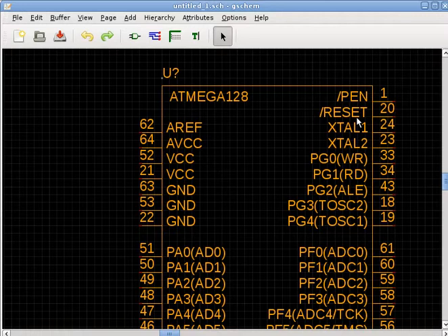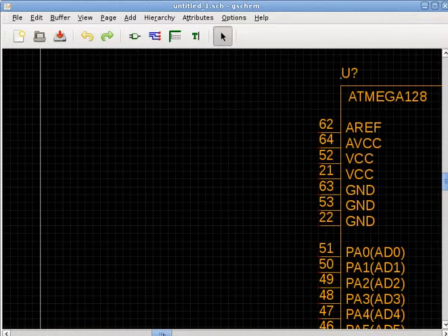No questions? Okay. So the next thing we want to do is to figure out how to power up an MCU like this. There are several things we need to do. The first thing is to understand what a voltage regulator is. You don't want to blow up an ATmega128 because it's $10-15 each, and it's a big hassle to desolder one of these things from a circuit board because it's a surface mount component. You can do it, it's just not very easy.